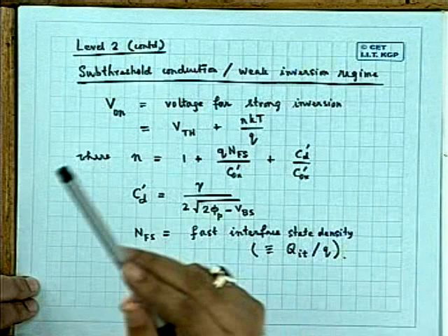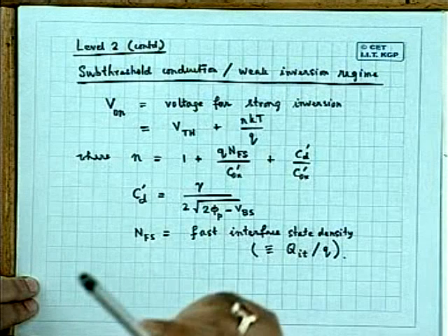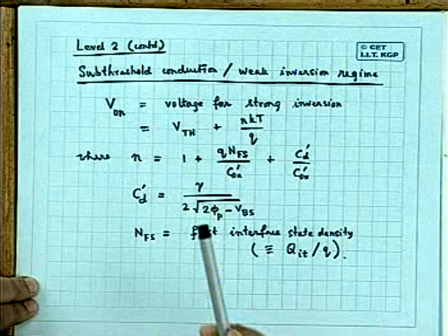In the accumulation region, as you make the gate bias negative, the charge increases exponentially at high speed. Then as you apply a positive gate bias for NMOS, the surface charge increases slowly, following a square root law. Then as the surface potential psi s exceeds the twice phi f criterion, again there is an exponential rise of the surface charge with psi s.